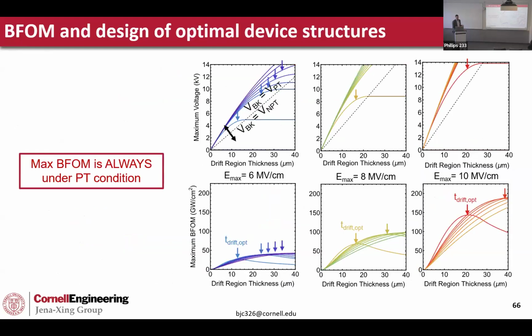It also is a useful thing to notice that this is always in the punch-through case. So even if we, several slides back, where I said, oh, we could do 30 micron, 10 to the 16, well, that will be much more resistive than if you used a punch-through case.